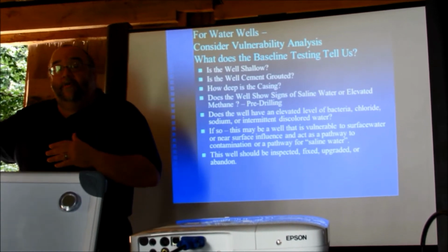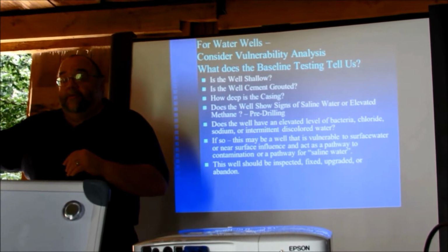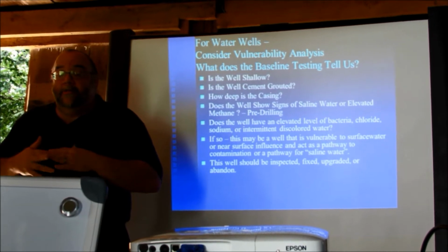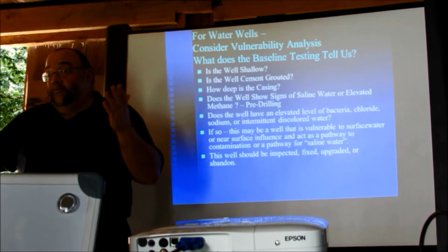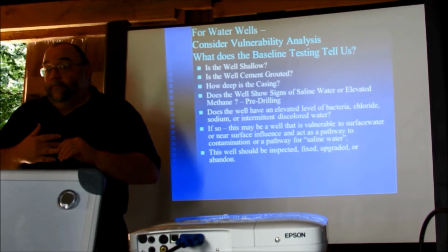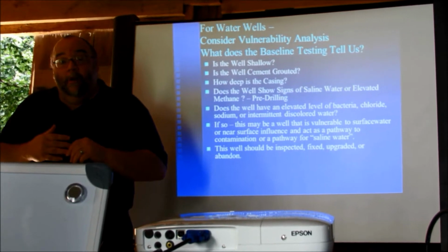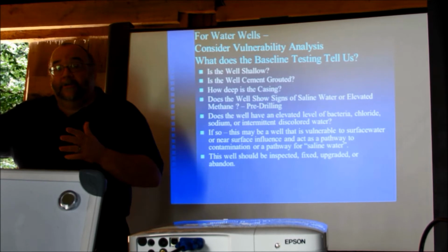And then when you raise the casing, then what do you do with it? You could just measure the depth of water. So how would you measure it? What kind of apparatus would you use? It depends. You can use a sonic water level sensor. You can measure with a line. You can use pressure transducers. You can do it inexpensively with a line, or you could buy a pressure transducer or a sonic water level sensor that measures the depth of water.